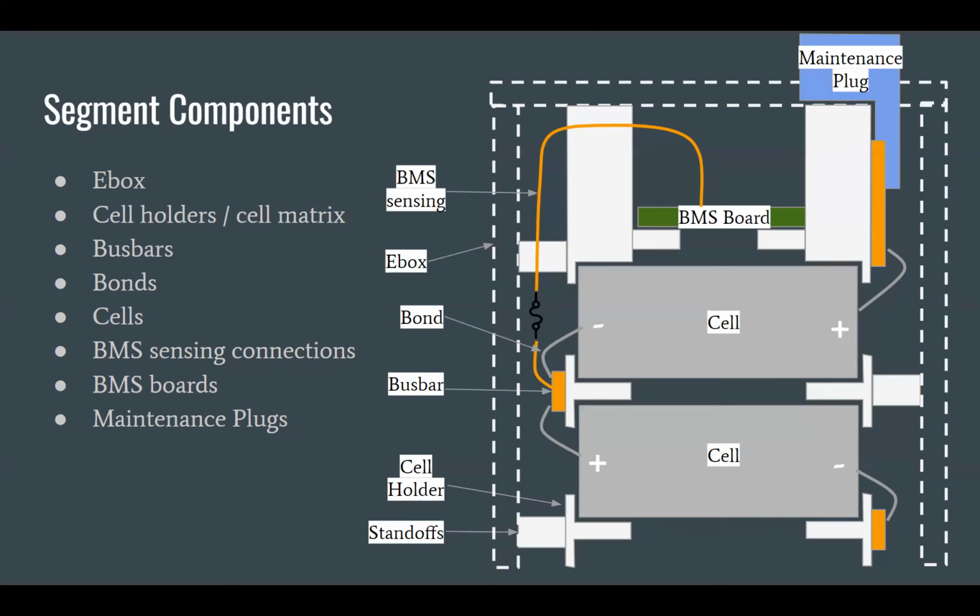I think one thing we can do with that, back to the box design, is that you can see it's difficult with the hole pattern in the box to get it right up next to the, especially for the side that has the shorter standoffs, to get those holes to actually get airflow through there. And that's the space that we care the most about getting airflow to, across the top of the cells and across the bus bars. So if you can come up with some novel solution on how to, with decreased standoff height, still get significant airflow across that area, that would be very beneficial.